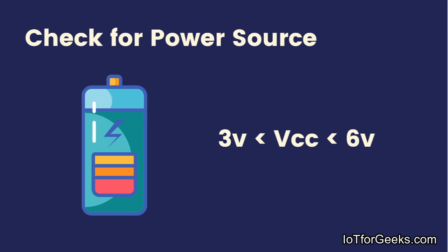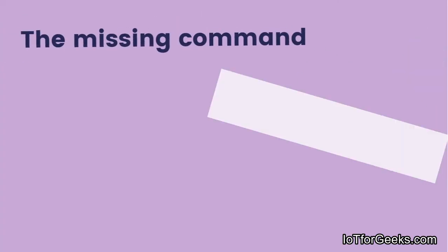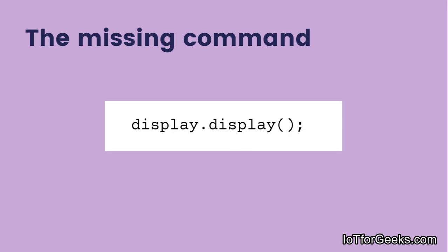If everything is correct, then you can just go for the next solution, and that is most important. Yes, this missing command. In the case of an OLED display, you have to use the display.display command after a bunch or a block of print statements. It will display the print statements only after this command. So make sure that you are using this display.display command.